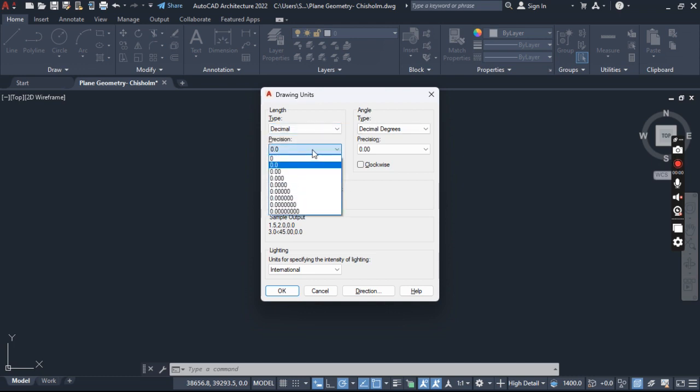All right, precision varies. This is if you have measurements that have a decimal place. So if you have something that is 1.192, the precision that I will select would have to be 3 decimal places or more. All right, if I select 2, it means that one of the decimal places would be left off because the value that I have has 3. So that's how you will use the precision. You have to know the measurements that you're using.